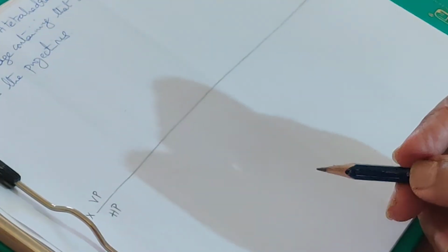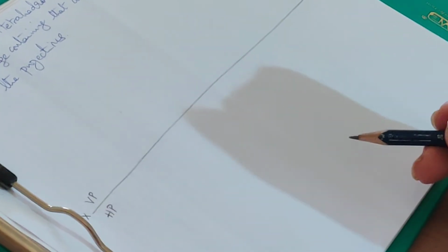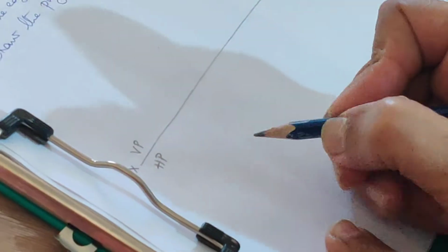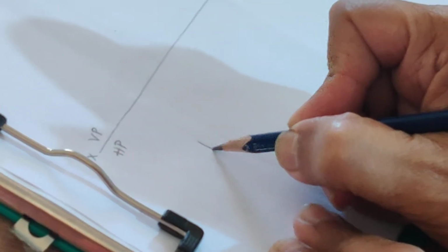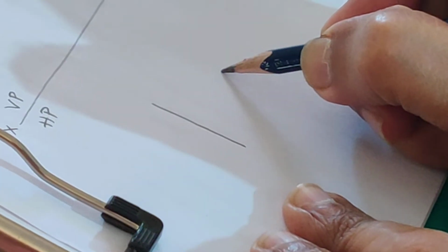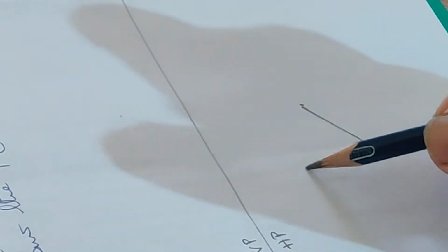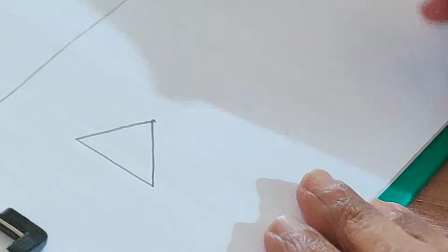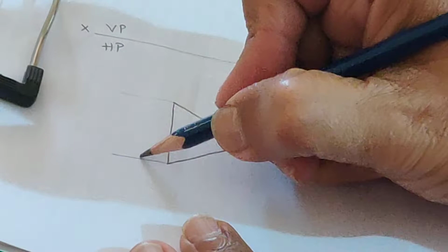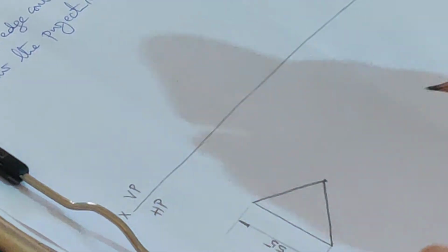In SP2, we start by drawing the top view first, and here the top view is going to be a triangle. In fact, it is an equilateral triangle. You should get a corner on the right side. So I will draw an equilateral triangle in the top view. Equilateral triangle, you know, the included angles are 60 degrees. The edge should be 55 mm. All the 3 edges, in fact.